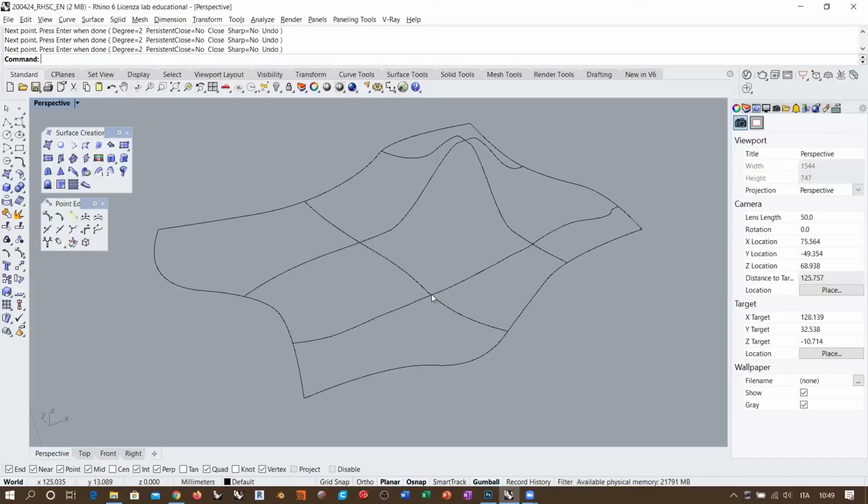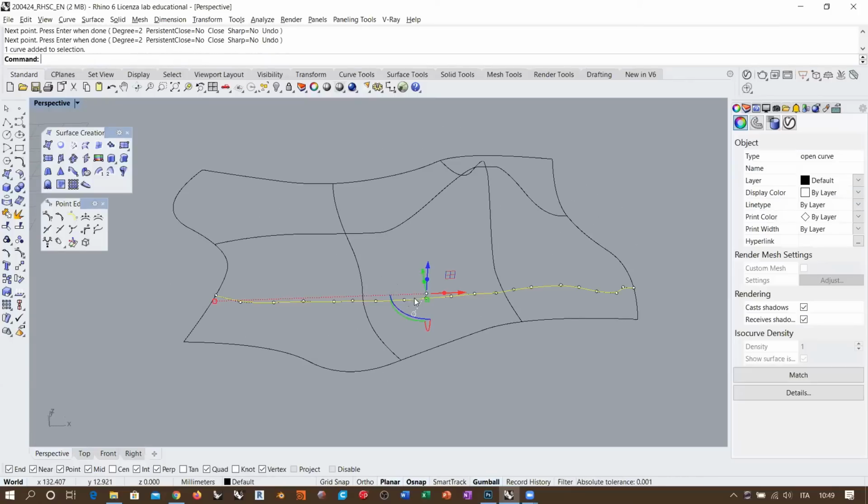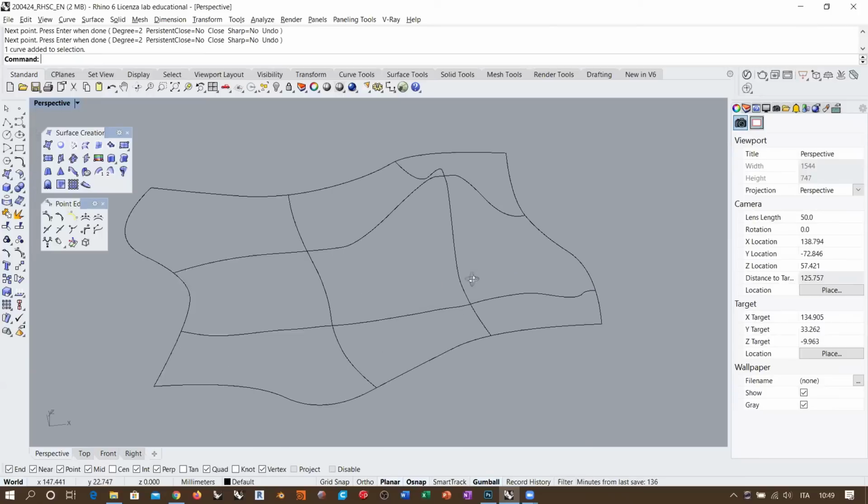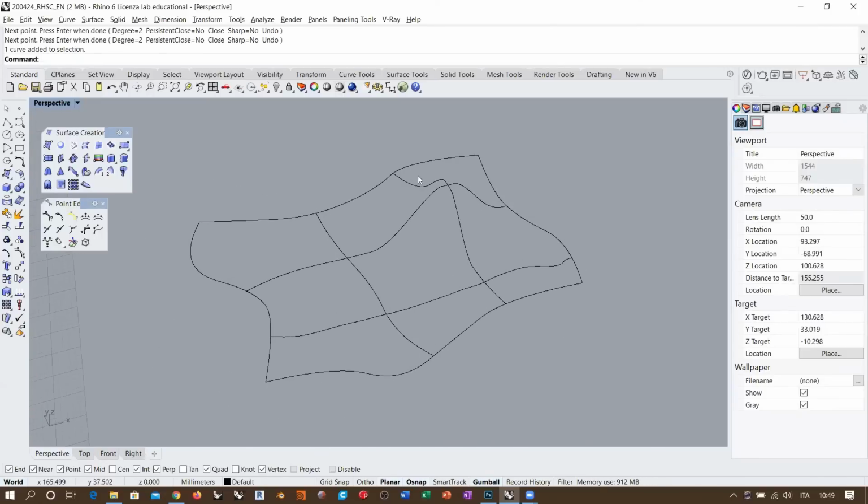And when you have a very complex topology, on the other hand, it becomes impossible to create a smooth deformation for these lines, because you should place the control points in a very, very specific distribution in order to avoid some, let's say, sudden deviation of the curve along the path, which would result in a not so smooth aspect. So it's very difficult to solve this problem simply by adding internal isocurves.